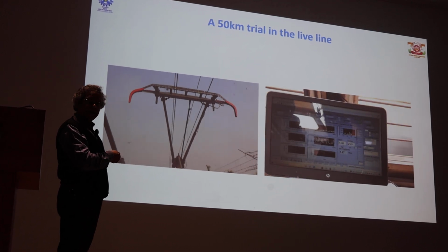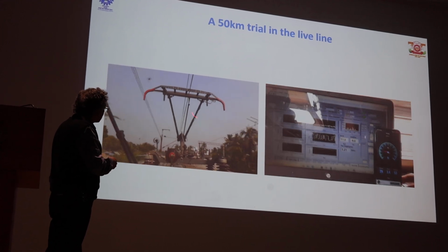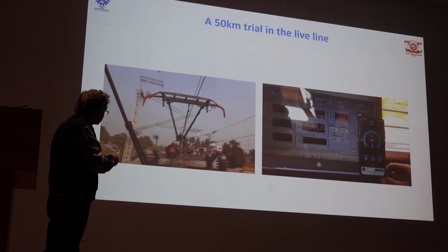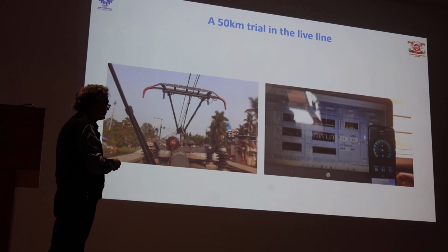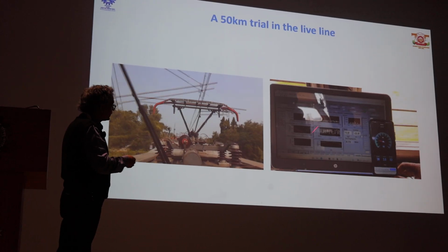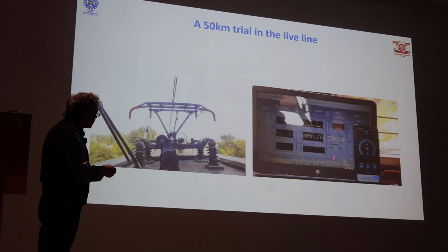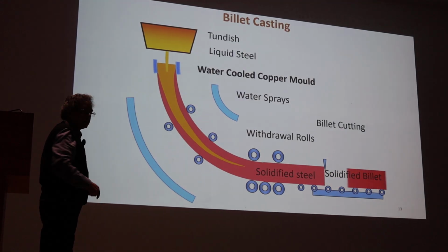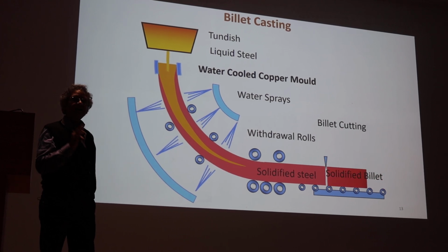We cannot expect any strain gauges or vibration sensors or temperature sensors to work in this. Also, the height of the pantograph is very important. When it is going down into a culvert, we can see the pantograph moving down, and in real time we can see, using again a displacement sensor, the height of the pantograph. We just took it on an optical fiber directly to our signal processing, and we can see it is around 0.5 meter. Then it will go up in real time. This particular example gave us a very big boost, and it is a real application.